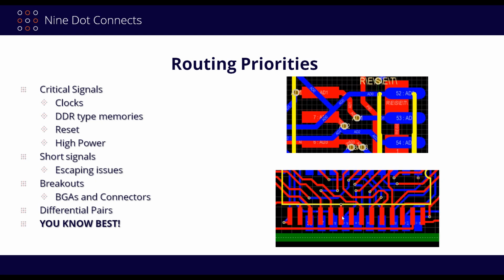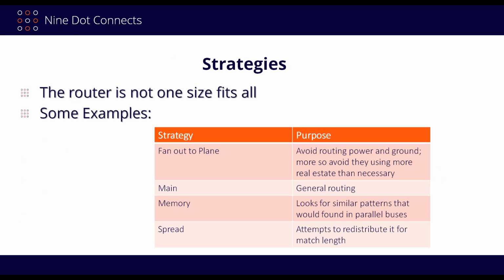Also down here, just another example, you've got two components basically sitting on the side of the board. So where are they going to escape out? They can probably do a little bit of escape to the left and the right, and they're obviously going to have to escape out to the top. But now they're practically on top of each other, so both of them are trying to get everything out through the top. It makes it very, very congested. Placement is certainly an issue, but the priority that you give to each one of these signals is also going to be an issue.